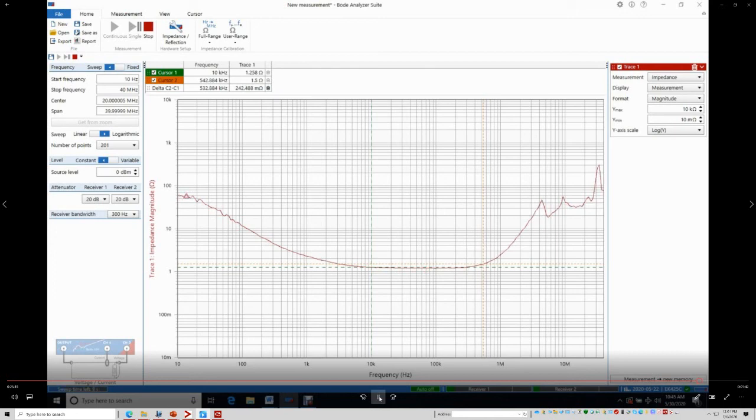Let's see what's happening. Since we're measuring at the input of the power supply, which has an input filter, the first component it's going to see is the series inductor. The series inductor at low frequency doesn't have enough impedance. Basically it's very low impedance, and there's a capacitor connected to it to ground. So what you're seeing here is the impedance of the input capacitor.